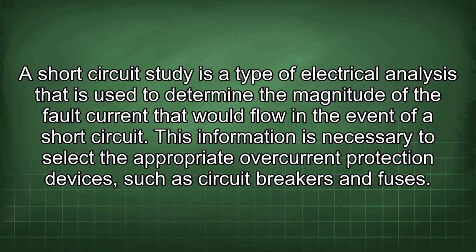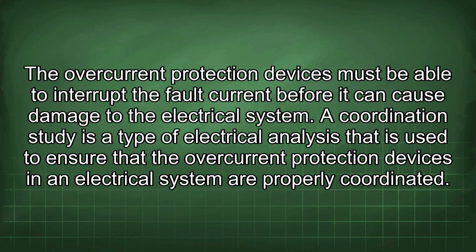This information is necessary to select the appropriate overcurrent protection devices, such as circuit breakers and fuses. The overcurrent protection devices must be able to interrupt the fault current before it can cause damage to the electrical system. A coordination study is a type of electrical analysis that is used to ensure that the overcurrent protection devices in an electrical system are properly coordinated.